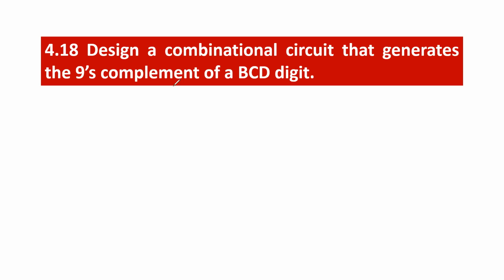Hello friends, in this video we will discuss an important problem: design a combinational circuit that generates the 9's complement of a BCD digit. This question is from the Digital Logic Design textbook by M. Morris Mano. To design the combinational circuit, first we should follow the design procedure.